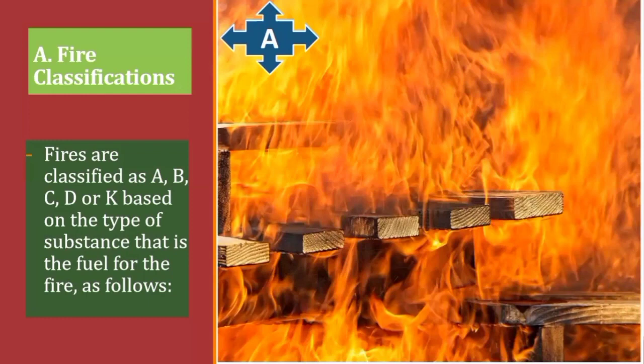Just in case you encounter that scenario, you had better not use water, but use the other extinguisher that can put out the Class A fire and also protect the electricity, to avoid the possibility of propagation or conflagration that electricity may cause.